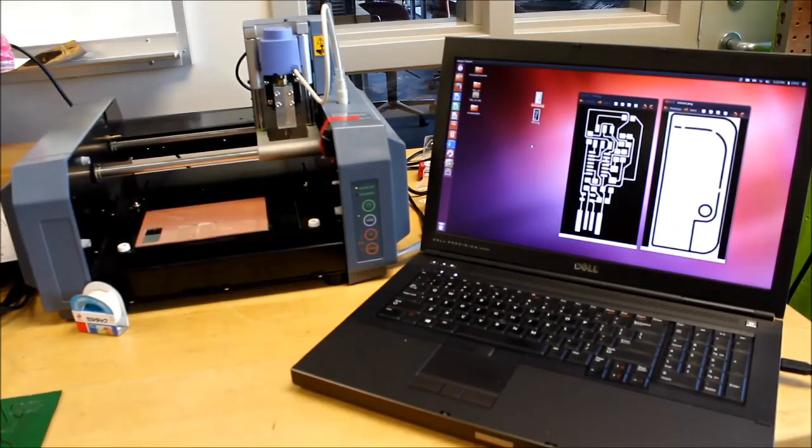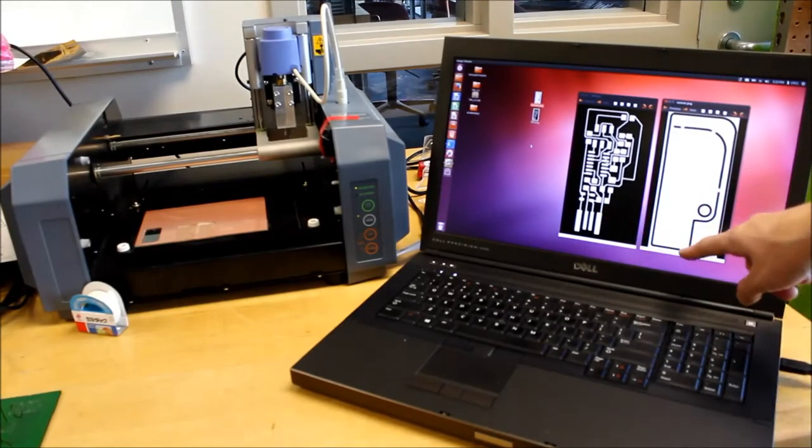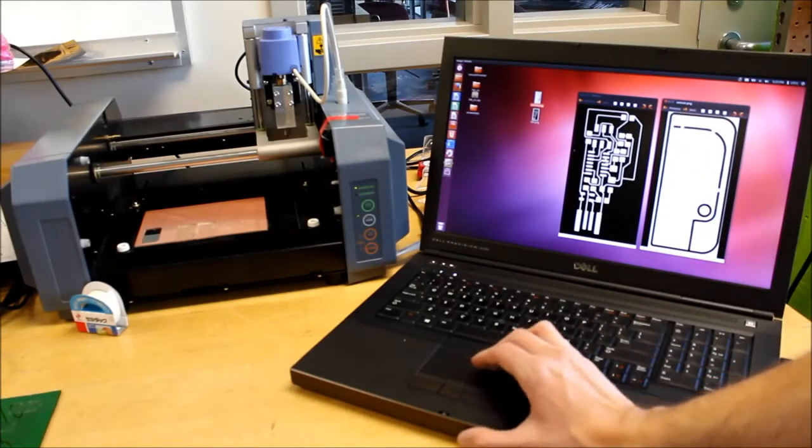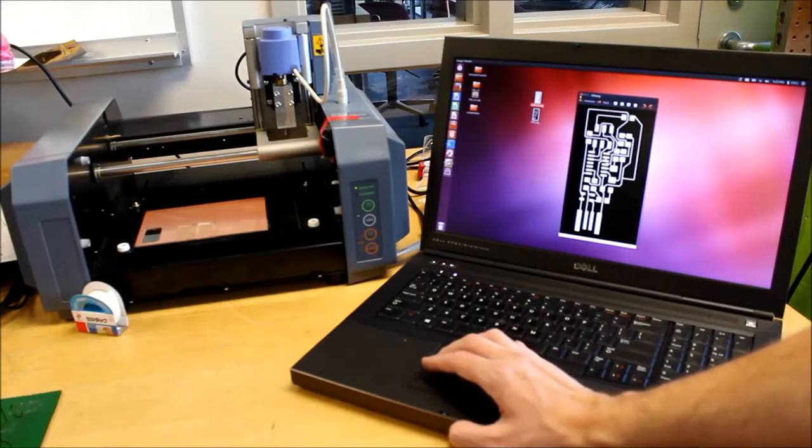Going to go over the process of milling a PCB on the Modela machine. So first we start with PNG images of our circuit and the dimensional outline of our circuit. This one's a little bit special because it actually has dimensional cuts on the interior of the board. Generally it would just be this exterior shape. So we have these that have already been exported from EagleCAD.